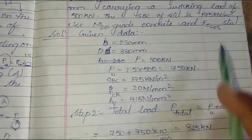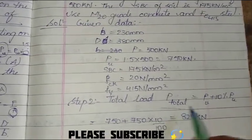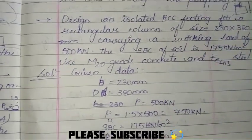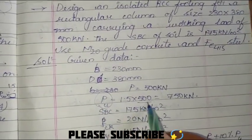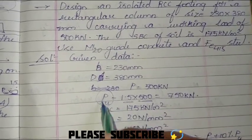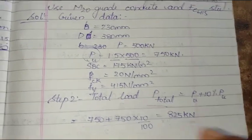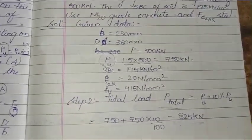Firstly, writing all the given data that has been provided. Step 2, I've told you we will be calculating the total load, PU plus 10% of PU. Remember, here we are given the working load. I told you we have to calculate the ultimate load by multiplying the working load with some factor called load factor, that is generally 1.5. So we got the ultimate load. Substitute in this equation, you will be getting the total load that is acting on this. This is the total load that is acting on the footing, which we have to design now.